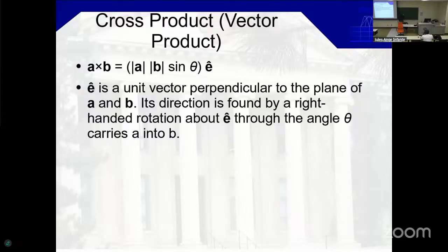So now I have a number of control points from my map. As a designer, I have them in terms of easting and northing, but I want to present them to the work crew in terms of station and offset, so that it's easier, because on the field, they will have stakes at every full station, right?